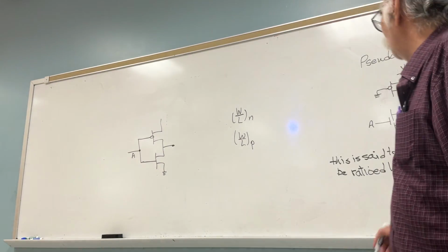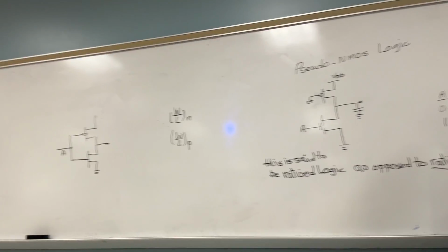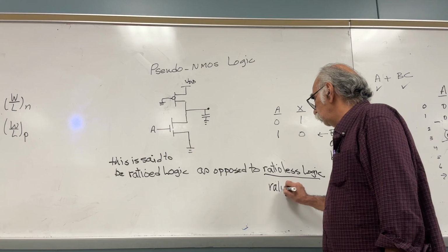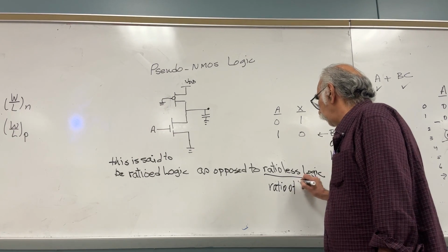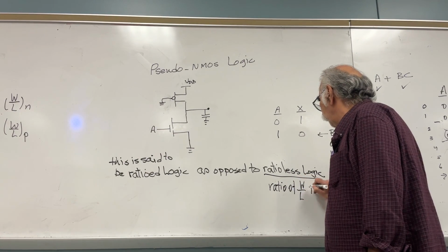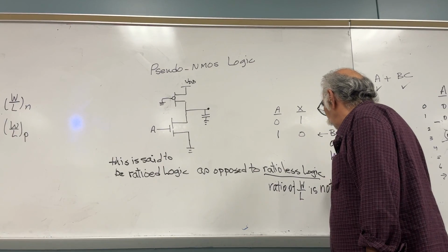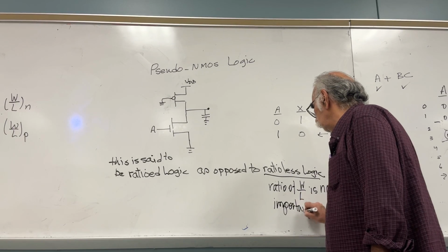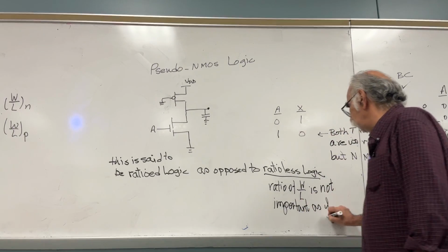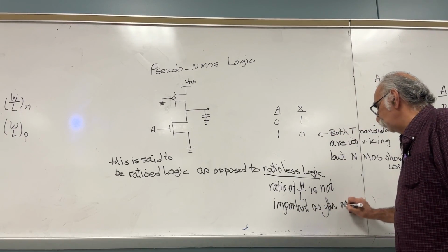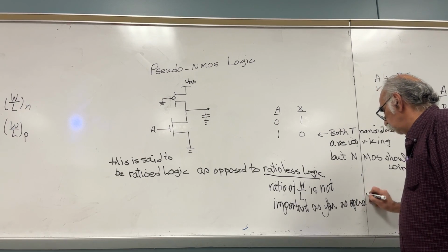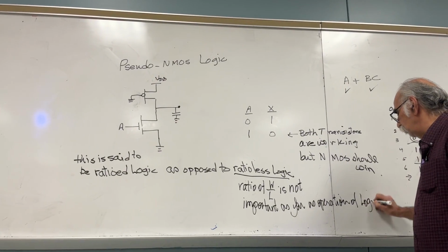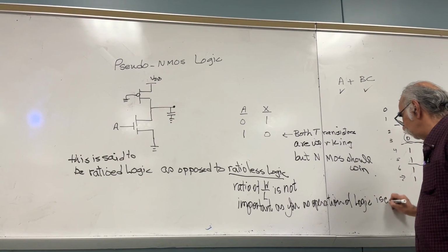Yes. This is what is referred to as ratioless. Clear? Which means the ratio of W over L is not important as far as operation of logic is concerned.